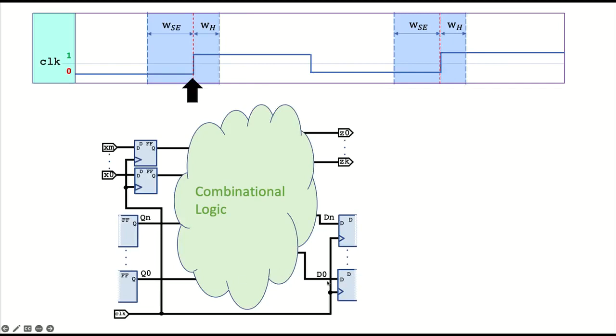They're just cut in half so that we unfold the circuit. And there are some external inputs. If these are really external inputs, then we ran them through flip-flops. If they come from another component that is clocked, then they're coming from flip-flops too, and we can consider that part of the state, if you like.